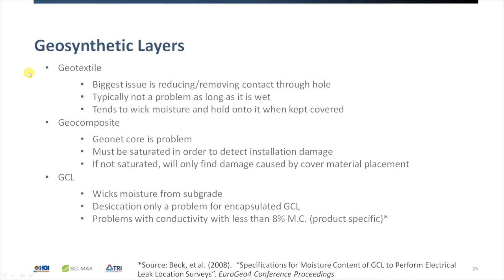So a geocomposite, where we have a geotextile separated by a geonet core, the geonet core is really more of a problem than the geotextile. Geotextile wicks moisture and kind of holds onto it and is conductive when it's wet, but the geonet core is more of a plasticky product that doesn't wick moisture as much.